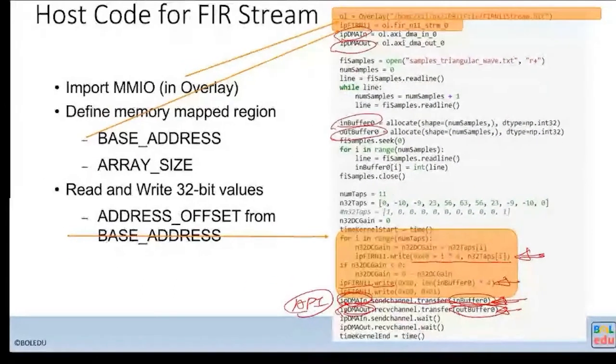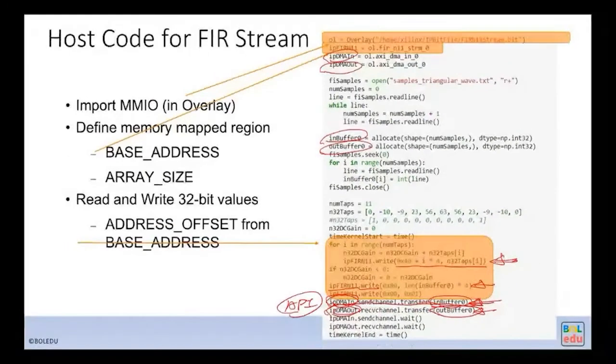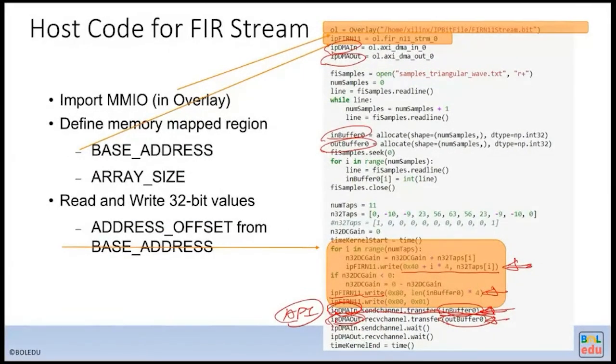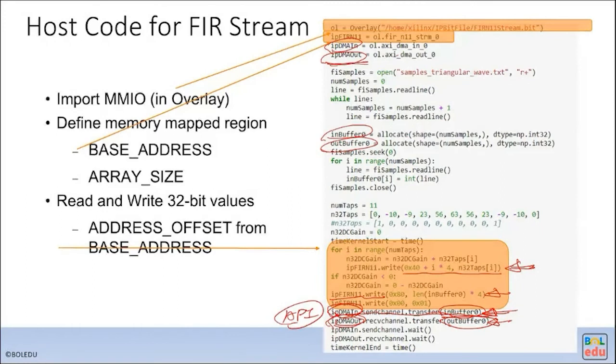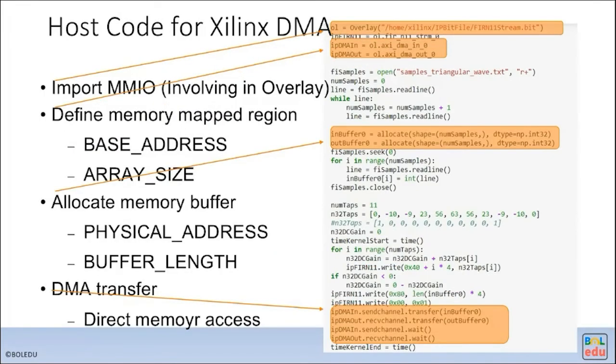Yeah. So if you are interested, you can really dig into the PYNQ open source code. Try to find those DMA IP, and then look at the detailed code. You will see that you will access those offset addresses in order to program the starting address and transfer length. Okay, so that's explained here. Okay, so that's PYNQ lab 1 and lab 2.